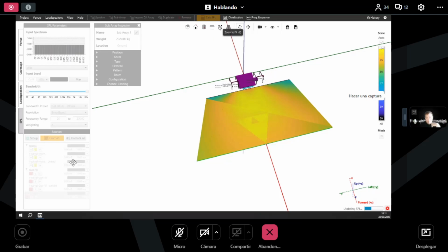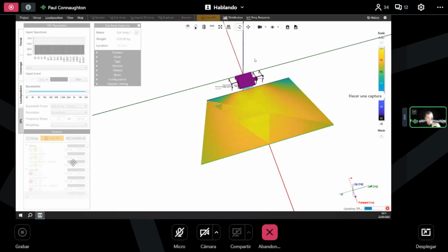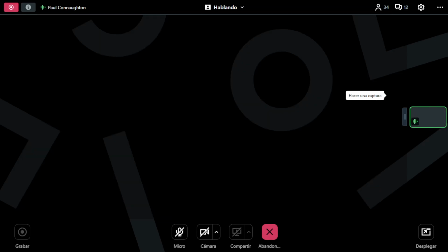It's got isometric view, you've got front back view, top view, side view. And zoom to fit, you've then got perspective or parallel projection view, orbit. So whether your left click is orbit or right click is click and drag. If you ever right click and hold down your right click drag, that will give you that. Left click will give you orbit around your model.